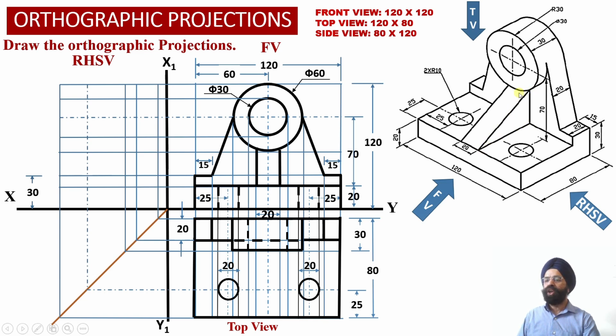Now corresponding to this inclined surface of the right angle triangular web, we observe that since this rectangular surface at the top of this triangular web happens to be inclined with respect to the horizontal plane, we are able to observe the apparent shape foreshortened rectangular projection in the top view projections over here. So this way we have been able to obtain the top view projections corresponding to this solid.